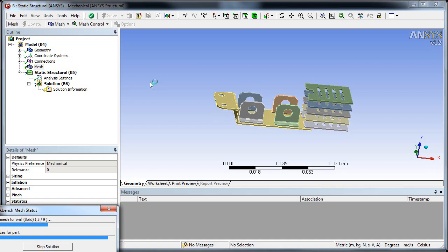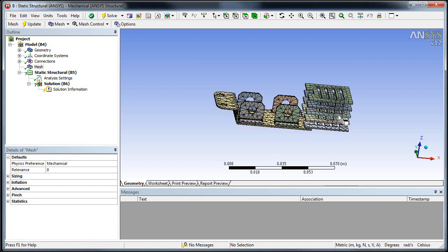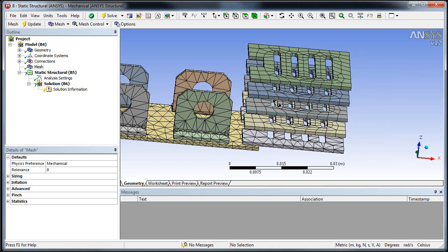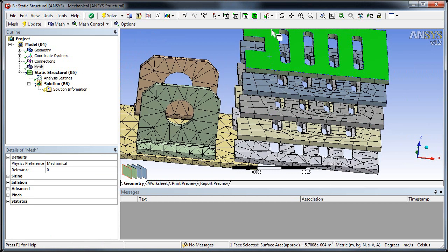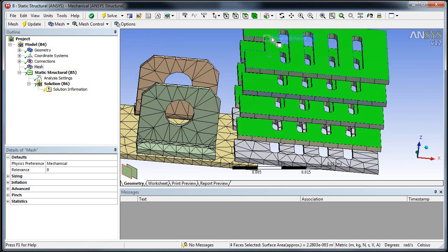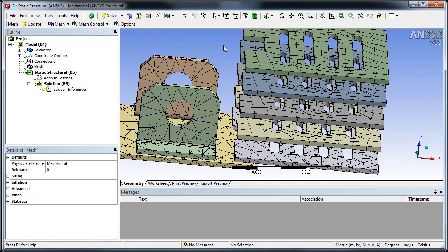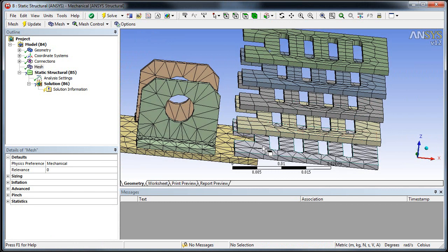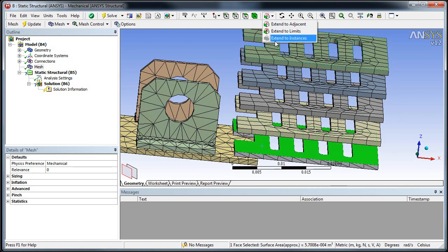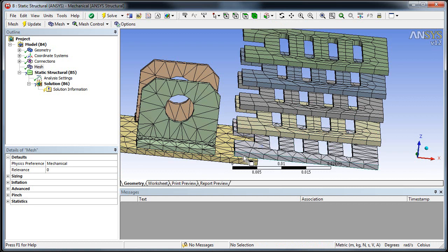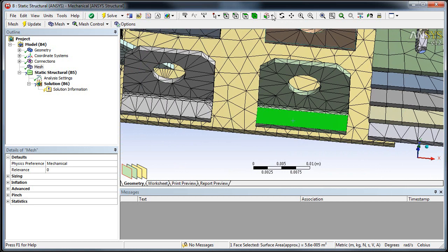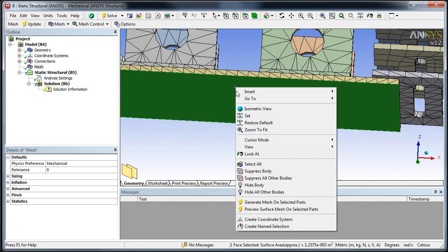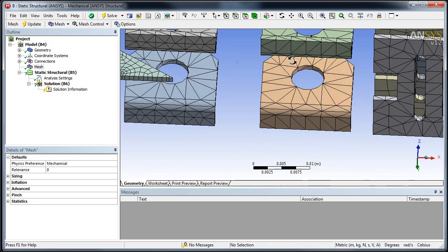You'll also see that there's another selection filter you can use when grabbing these parts. So if we zoom in, we can see that all of these meshes are the same. If I click on one face, you'll notice I can extend to instances. And one thing you'll also notice is that only the top 4 solids are instances and the bottom one is not. And that's because when spot welds are applied to the solid, you'll notice that they'll have a different mesh because of that. So they won't be detected as instances, which can sometimes be a problem.